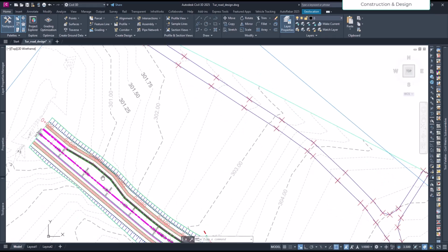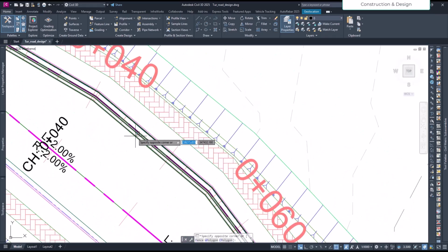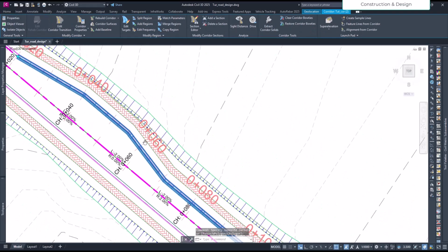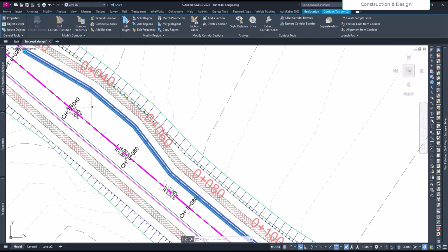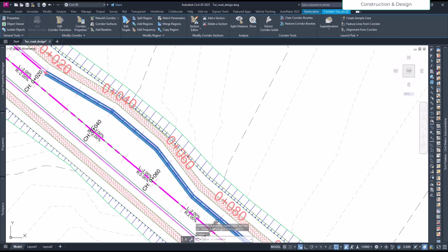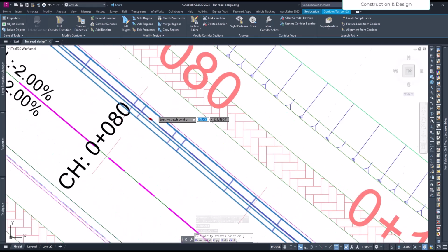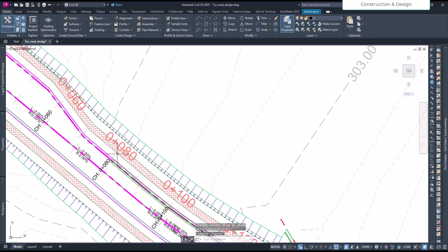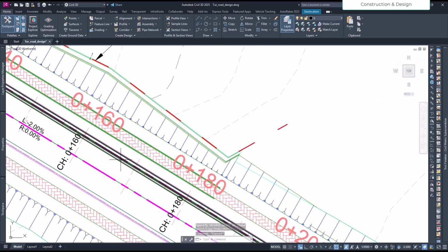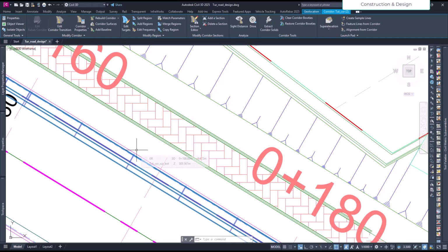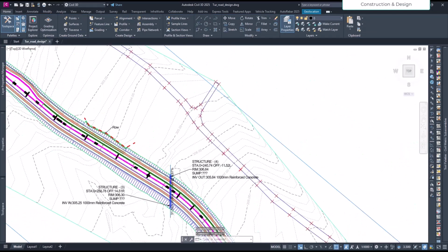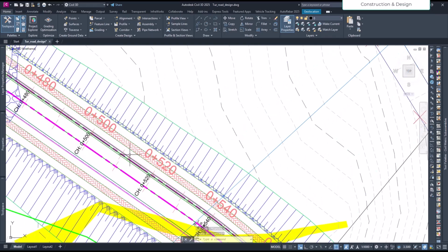Right now, we created a guardrail last time for this location as well. However, this one is a bus bay, so here we can't put it. Based on whatever norms you have from your traffic safety management office, you can remove it and add it. We can add a Jersey barrier as well with the same alignment that we created for the guardrail. So let's first locate a position where we're going to add it.